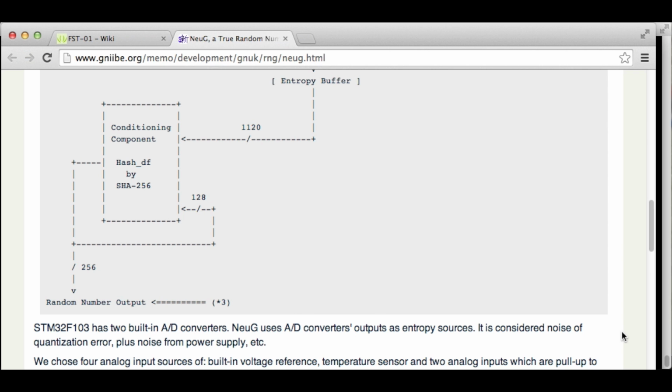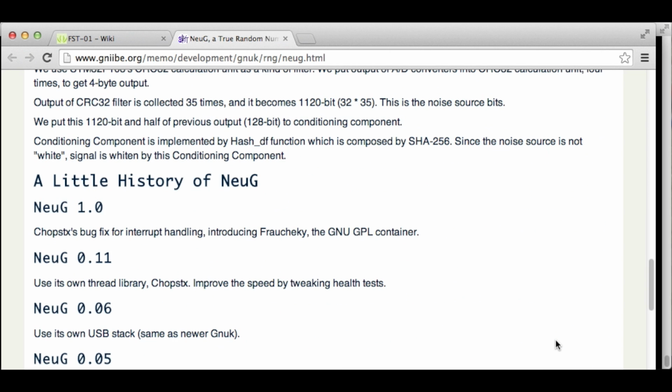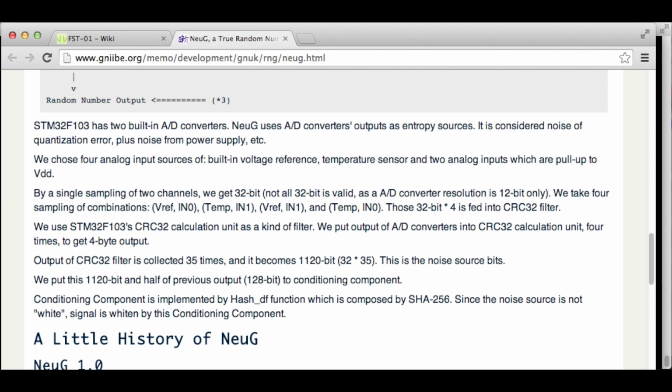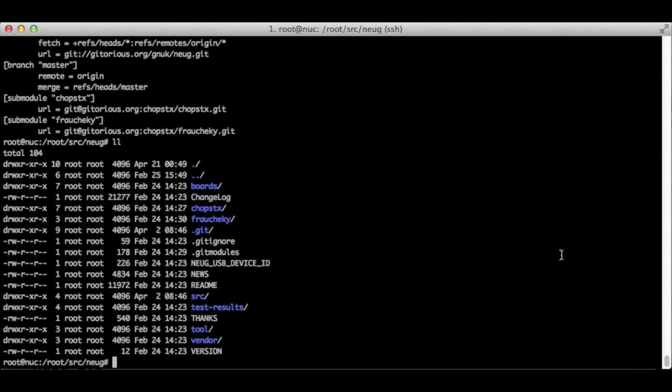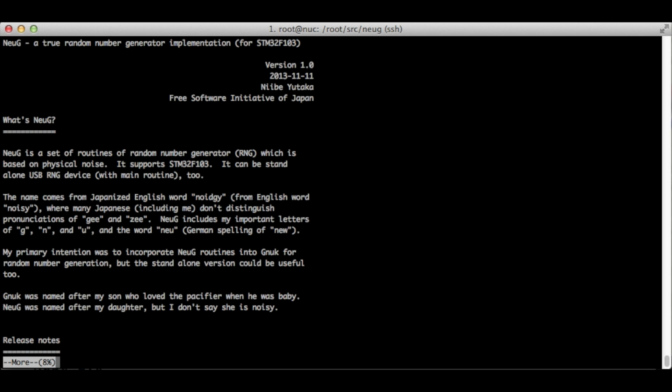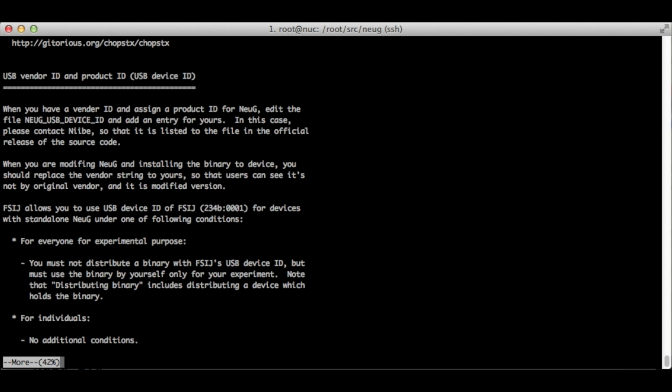Now what you have to do is compile the software and make it work on this device. So you have to go after this source tree here and dig into how to compile it. You essentially cross-compile for this processor, and it's a little bit involved. You can read the README to figure out how that's done, and you'll get the idea relatively easily.